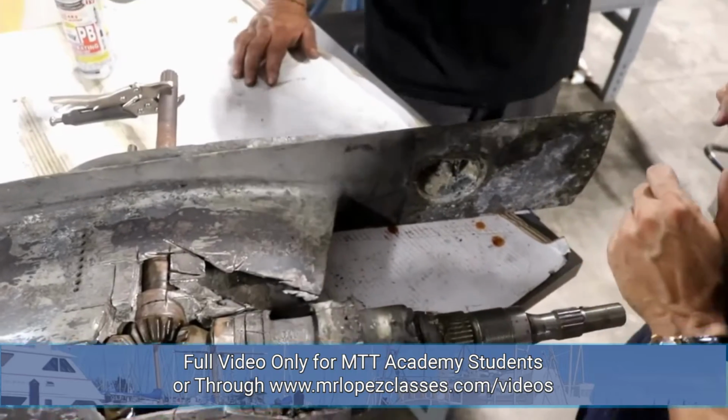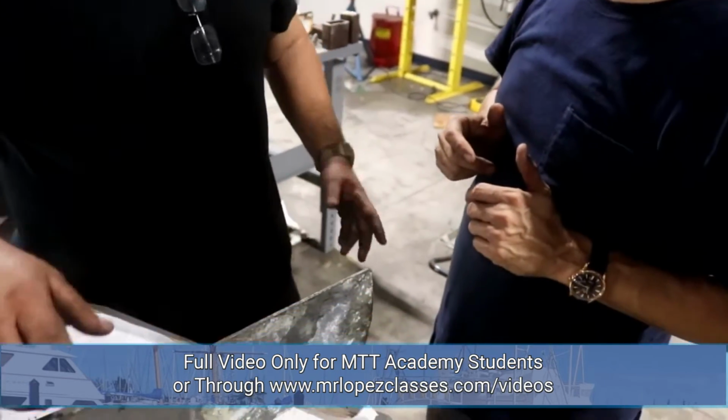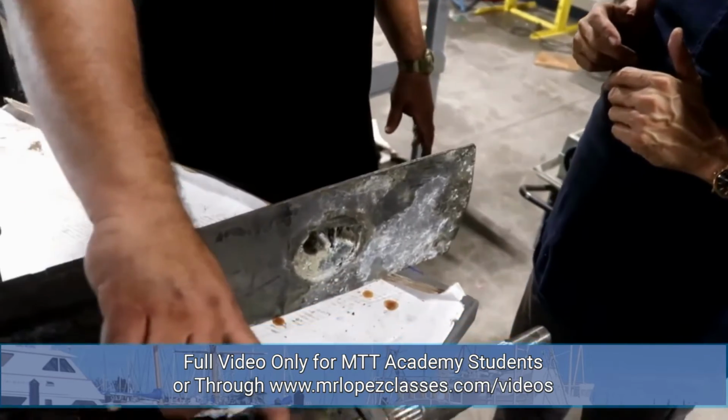And you have more torque with a dual prop. And in reverse, you have just the same power as you do in forward. Yeah. It's incredible. This is probably one of the best drives. The only downfall of this drive is that since there are a lot of parts within each other, they don't have a good bonding system. So the Bravo 3 has a tendency of getting eaten up.